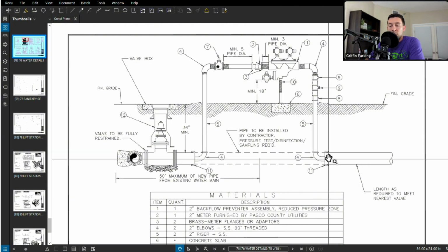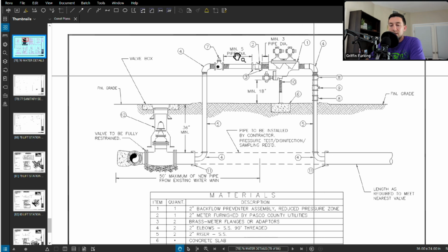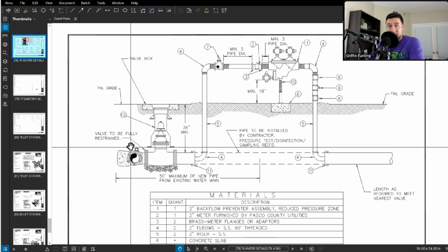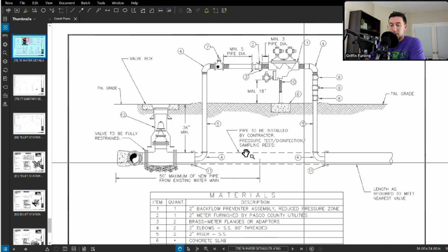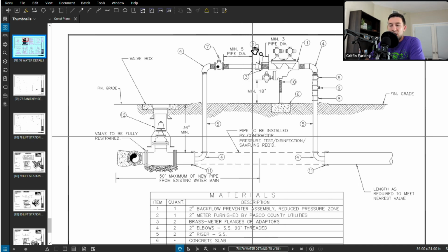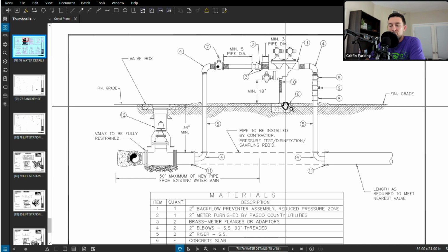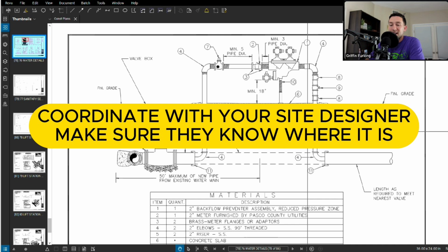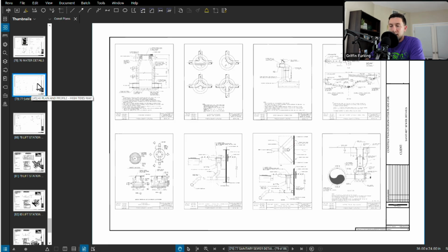So when we're kicking off construction, the contractor is going to have to install this device temporarily so that water does not get backflowed into the system. Because like I said, we're going to have to certify this pipe before it can actually be connected into the system. And always be cautious of how big the pipe is and how big the backflow prevention devices are, because your landscape architects will always give you a hard time. They definitely need to know where all of these are so they can shade them from view, because sometimes they're big and ugly.